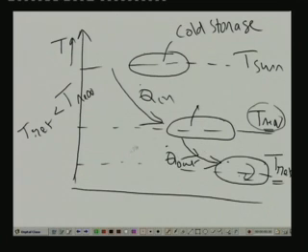That means heat transfer takes place from the surrounding to the cold storage because of this delta T, and this has to be taken care of by extracting heat from the cold storage using a refrigeration system. Again, some delta T temperature difference is required so that this heat transfer can take place. So finally the heat is coming to the refrigeration system, and if it is a cyclic device, whatever heat is coming to the refrigeration system must be thrown somewhere else. We will see how it will be finally rejected.